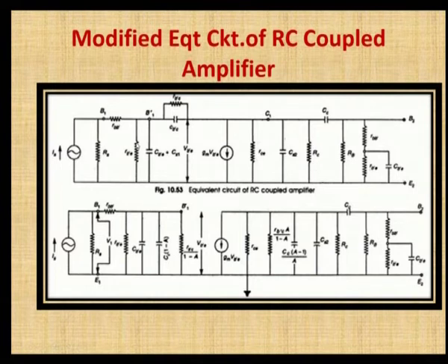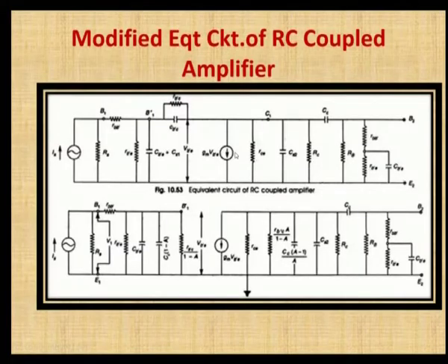In between any 2 terminals the resistances are considered, in between base and collector, base and emitter, or collector and emitter, and so it is given as RB dash, RB dash E and RCE. And in between the base and the collector, the capacitance is also considered, between base and the emitter, and also collector to the emitter. In between any 2 terminals the capacitances are also considered, and it is given in the equivalent circuit. Here a current source gm VBE is given.